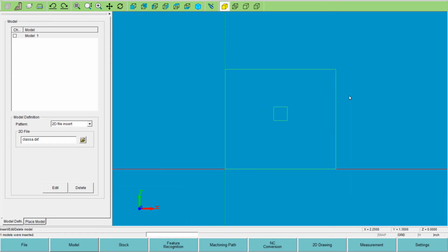Sometimes another engineer is programming the part and puts your part out in space or someplace so it just prints out nice on a piece of paper. So we need to use place model to put the origin somewhere we're going to pick up on with the wire machine, or put it in the center of the geometry, something like that. So I'll show you how this works.